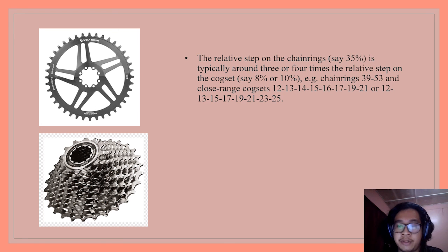And this arrangement provides much more scope for adjusting the gear ratio to maintain a constant speed on any surface and elevation. But any change of chain ring must be accompanied by a simultaneous change of 3 or 4 sprockets of the cassette if the goal is to switch to the next higher or lower gear ratio.